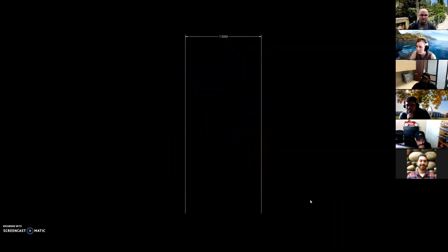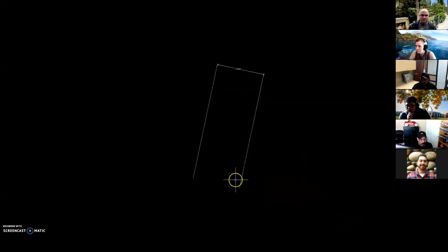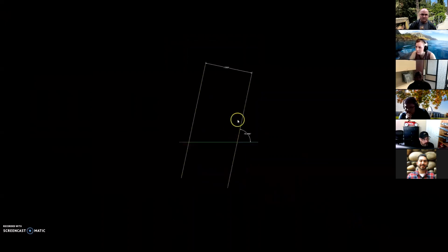Now with this step done, let's jump to the next, where we'll see what the system is doing at the slope elevation, elevation number 2. For that, let's rotate this 12 degrees off the vertical plane. Now we have rotated and we have obtained this. Notice the lines have been rotated as a unit, where the distance between the parallel lines is still 7.5.